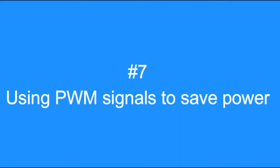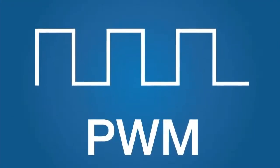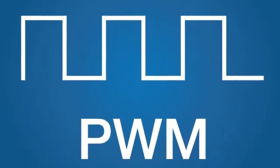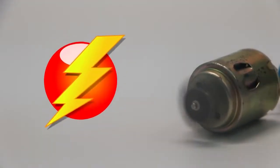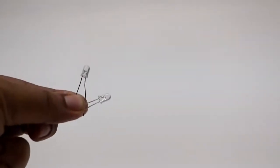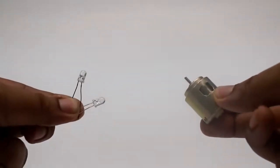Tip number 7. Using PWM signal to save power. You probably might have heard about PWM. It is a modulation where the duty cycle of a pulse is modified. Using this PWM signal, you could drive LEDs or motors, which ultimately can reduce the power consumed by them. This is possible since LEDs and motors are quite slow to react to a high frequency PWM signal.